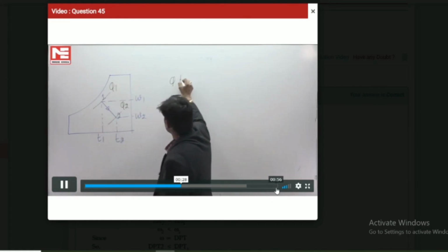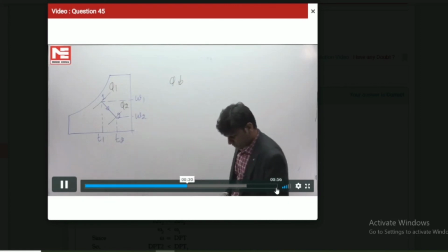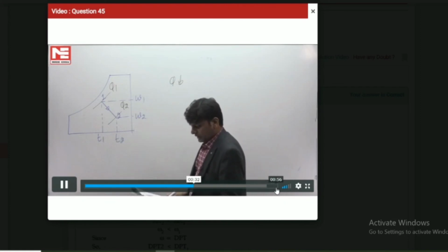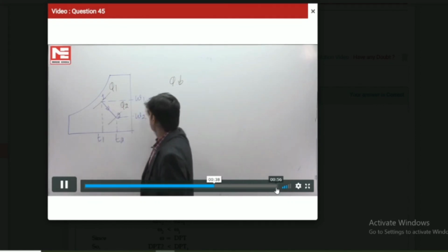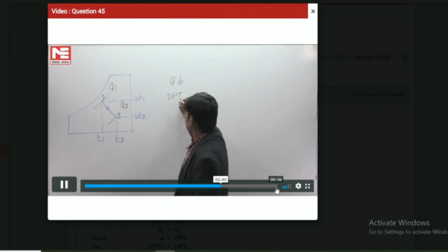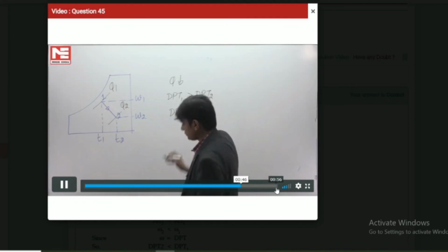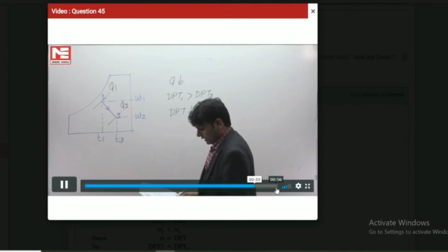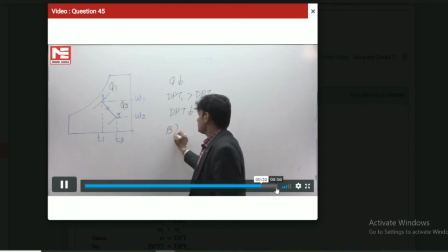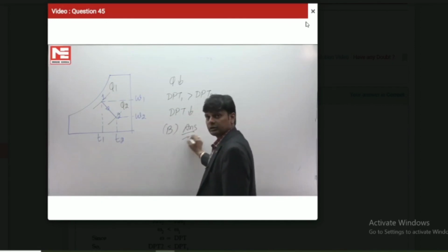So first property, the relative humidity decreases. Okay. Now second, wet bulb depression, it increases. Next, dew point temperature. Dew point temperature also decreases. So dew point at 1 is greater than dew point temperature at 2. So we can say that dew point temperature also decreases. So points number 1 and 4 decrease. So the answer is option B. This is the final answer.